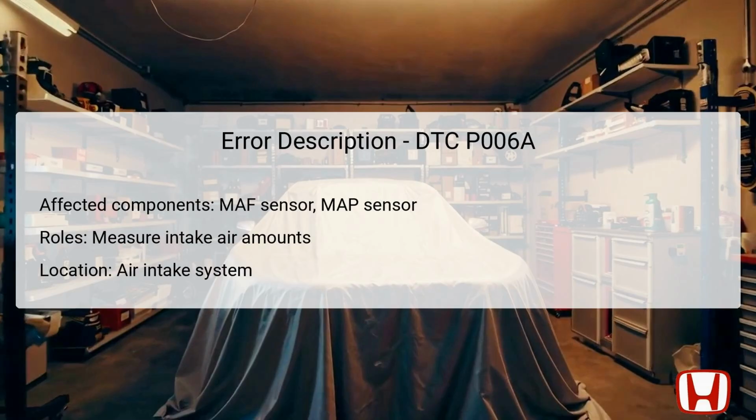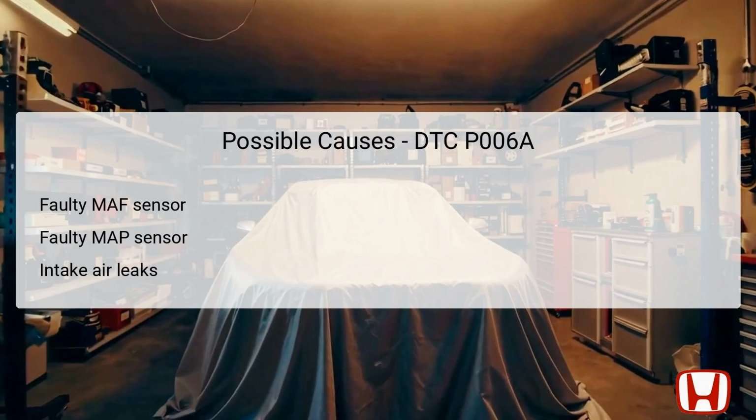Both sensors contribute data used by the PCM for engine control, leading to efficient fuel consumption and stable engine operation. When the data from these sensors diverges beyond acceptable limits, the PCM triggers DTC P006A, indicating a performance issue with the MAF sensor circuit. Several issues may lead to the trigger of DTC P006A.